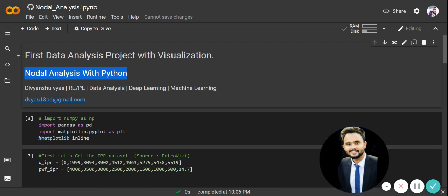So what that does to the oil is it reduces, it depletes its energy as it comes towards the wellbore. Most people think of it in different ways, but this is a very nice visualization. Imagine you are sitting on top of an oil droplet which is starting its journey from the reservoir and trying to flow towards the wellbore. You will experience that down the lane, as it flows from the reservoir to the wellbore, it loses its energy as it flows through the porous media, right? So this is exactly what IPR is.